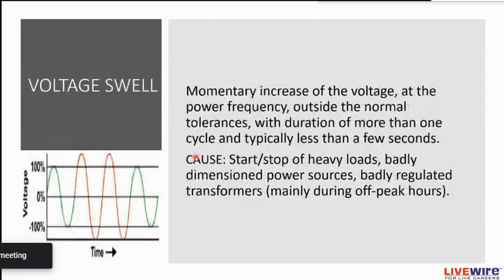And then talking about the voltage swell, this is just the opposite of the voltage sag. So the voltage swell is the opposite of the voltage dip. In a voltage swell, there is a momentary increase of the voltage. In the dip there is a decrease, here there is an increase of the voltage. This is also characterized by the magnitude of the voltage and the time duration.